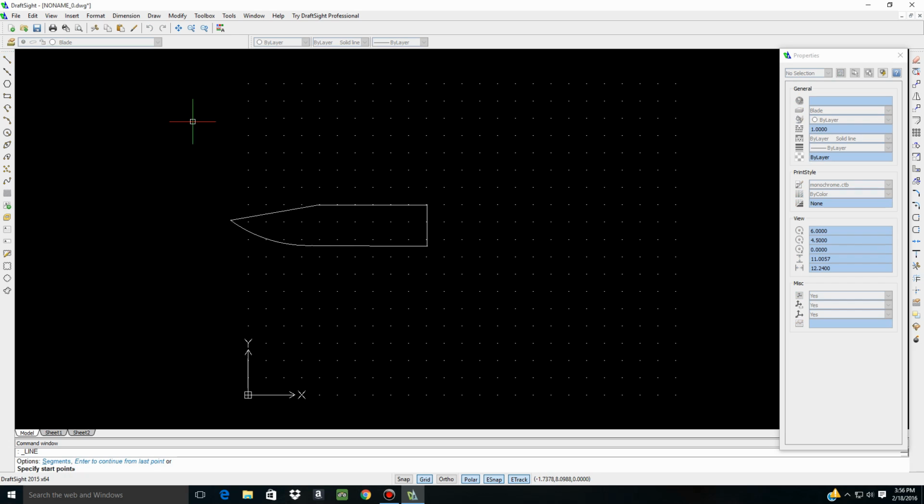So we're going to select the line, and wherever you think the bevel is going to be. As you see, I'm trying to put it over here, but it wants to highlight the end. So right now I'm going to have to turn off the E-snap. So I'm going to turn it off, and now it's still telling me that it wants to select the end, but it's okay, it'll let me select over here. You see?